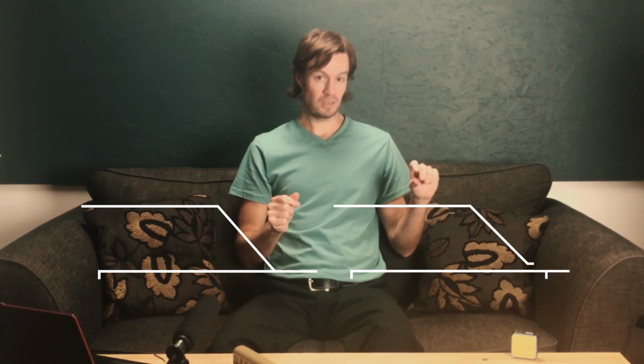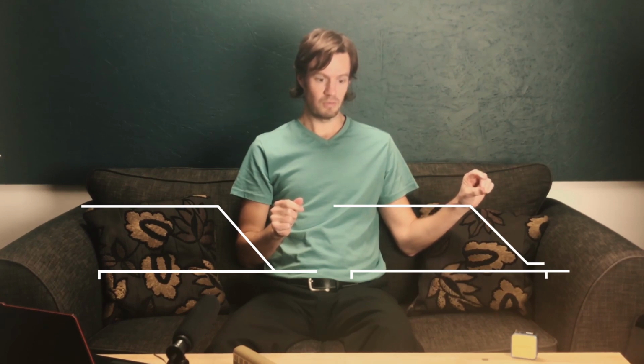This means that for computer control systems, the train must have a constant speed when it enters the track section. The system sometimes also has a sensor at the end of the section, such that the train enters the block section with a constant speed. It runs for a time, starts the deceleration, but then it keeps going at a threshold speed very slowly until it hits the final marker within a section, and it can then stop precisely.